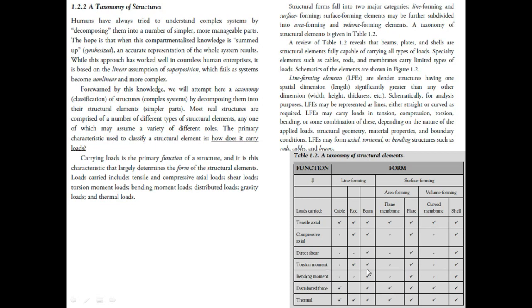For torsion moments, the cables will not undergo any torsion, but the rods can undergo torsion. Even the beams can undergo torsion as well. As for bending moments, only the beams have them. The cable and the rods do not have any bending moment scenario.